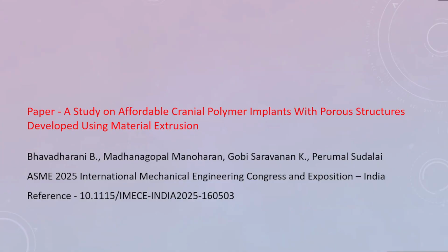You need to create your own lattice structure, incorporate it in your design, and then do some thermal analysis. Sometimes the simulation may look much better, but if you print it, there will be additive manufacturing constraints like distortion or thermal gradient effects also. I would suggest you create your lattice structure, print it, and study some physical things. Then you can make a trade-off with topology optimization and the applications which you will require.